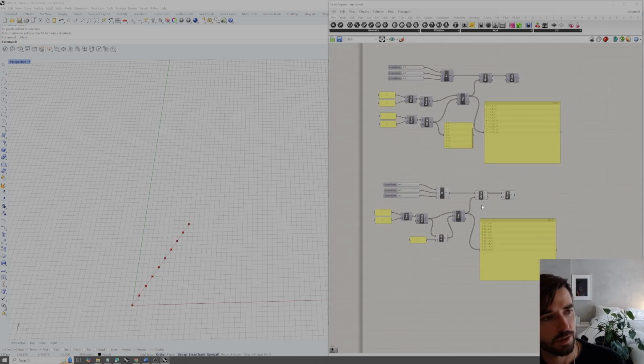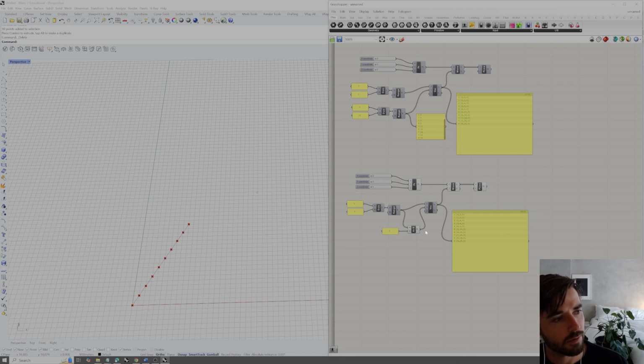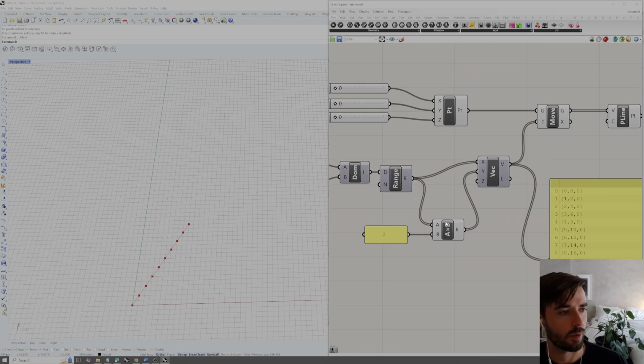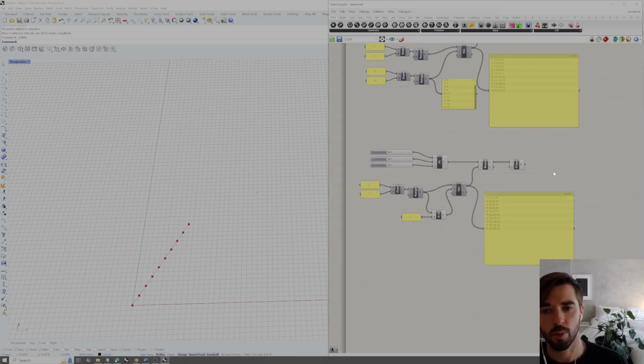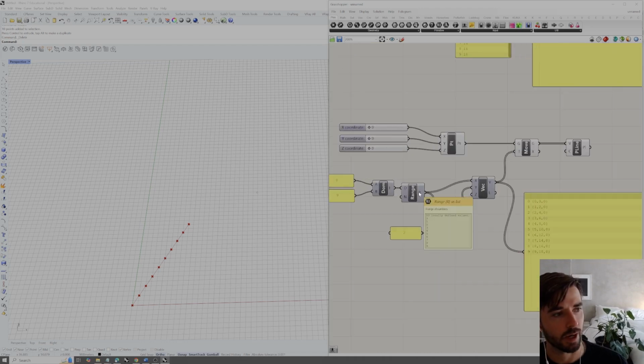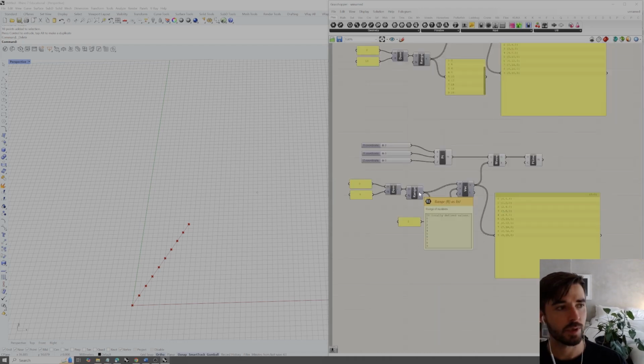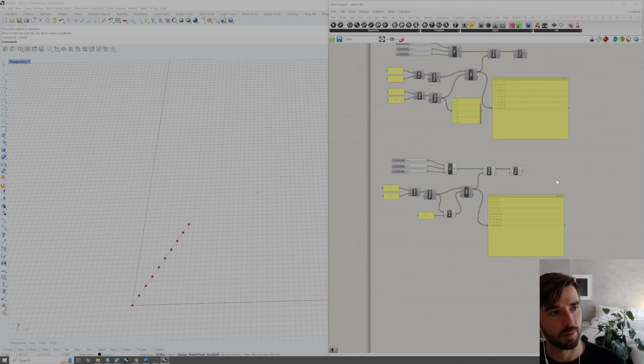To take full advantage of Grasshopper and its parametric operations, we have other types of input parameters that can not just change with a multiplication operator, but we can do it more complexly by feeding the values of this range, so 0 through 9, into an equation, and use that equation to adjust those number values, and then input that instead into y. So let's say we wanted to map a parabolic equation as this polyline, or map this polyline to a parabolic formula. We could do that using what's called a graph mapper.